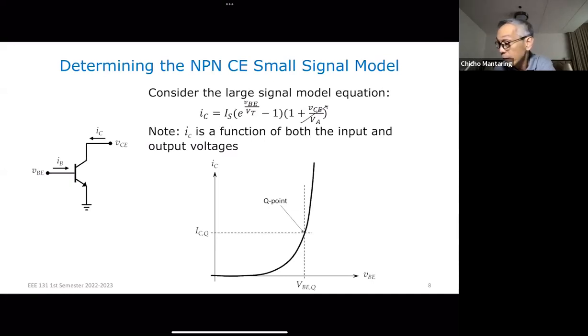Okay. This is going to be what my plot looks like, which is the diode curve. It looks like the diode curve, except that instead of reverse saturation current, we're talking about your scale current. So this is how IC will look like with respect to VBE. Again, take note, capital letters yung subscripts ko. And my transistor will be operating at a certain operating point or Q point.